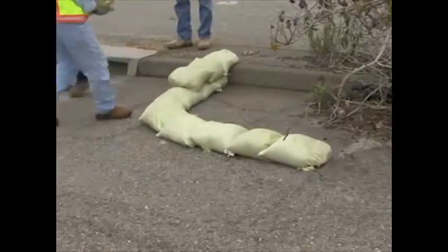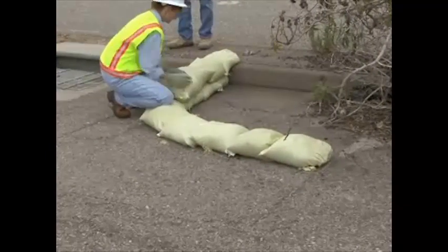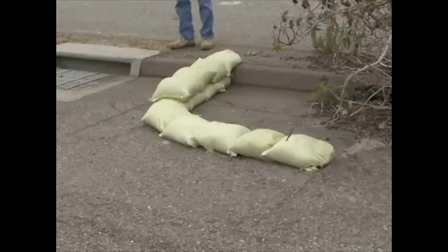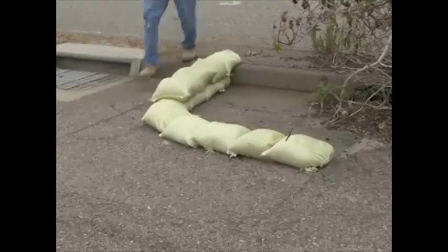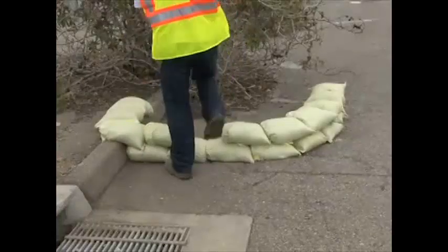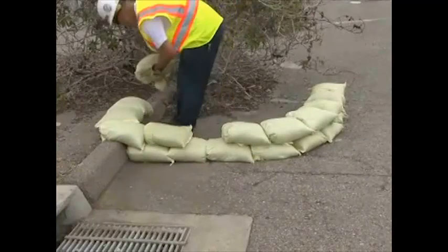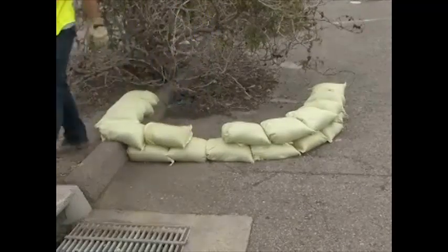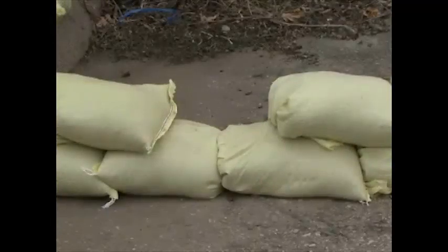Stack gravel-filled bags to form a gravel bag barrier. Place the gravel-filled bags so that the bags are tightly abutted and overlap the joints in adjacent rows. Create a spillway by removing one or more gravel-filled bags from the upper layer of the gravel bag barrier. Use gravel-filled bags only in shoulder areas and when placed behind temporary railing.